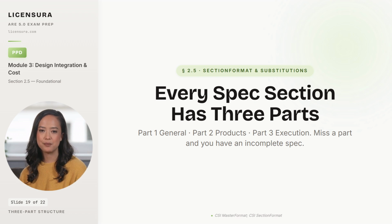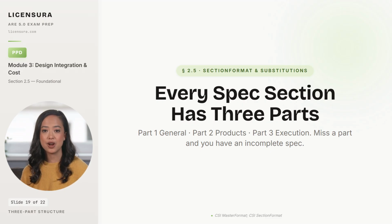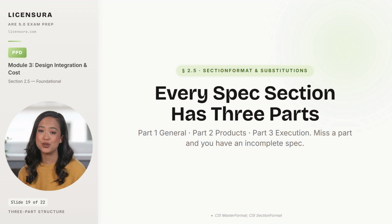A spec that puts product requirements in Part 1 or installation methods in Part 2 violates the format and tells the bidder the architect does not know how to write a spec, which is a credibility hit that can cost the firm the next job. And worse, a substitution clause in the wrong part of the section is unenforceable, and the contractor who substitutes a cheaper product wins a dispute the architect should have won. Let me walk you through the 3 parts and what goes in each.